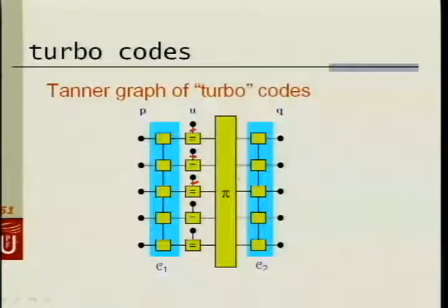We see that in this case we need a relatively simple convolutional code because we have to perform the calculation involved with this function many times. So we need a relatively simple trellis structure, otherwise the complexity of the calculation would be overwhelming.